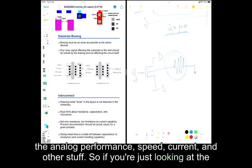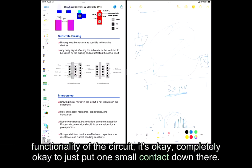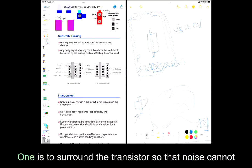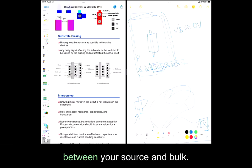So if you're just looking at the functionality of the circuit, it's completely okay to just put one small contact down there. But that's why, if you're doing analog IC design, you will try to put as many contacts as possible. One is to surround the transistor so that noise cannot couple in, but also you want to minimize the voltage difference between your source and bulk.